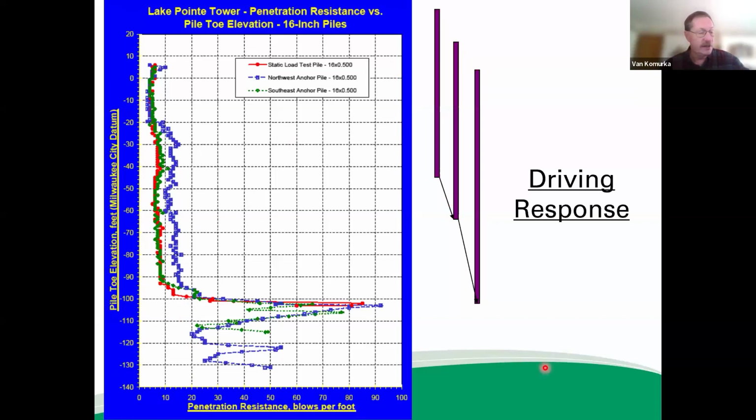That's all that's intending to show there. So, not too high of blow counts. We're at 10 to 15 blows down to that. Remember that hard layer we saw at negative 105, that hard layer of fine sand. Drive through that, and then it's somewhat layered below that until we get down to the till.